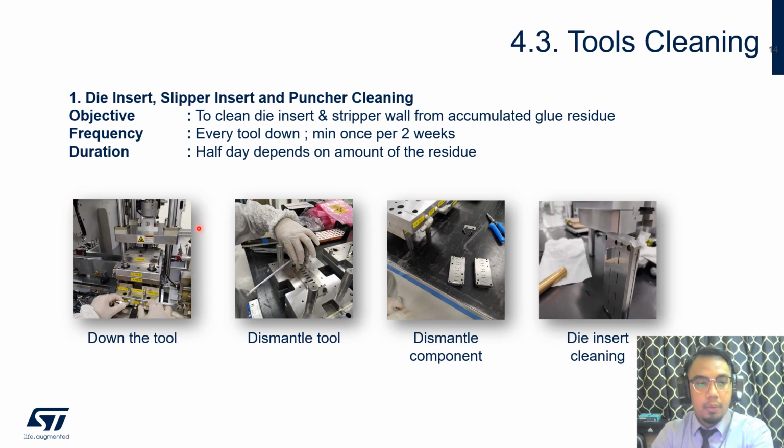This is the process of the tools cleaning: we need to take down the tools, dismantle the tools, and then dismantle the components, and we will do the die insert cleaning. This will prevent foreign material from sticking on the lid locking tab.